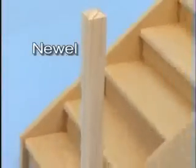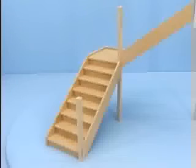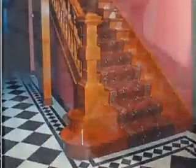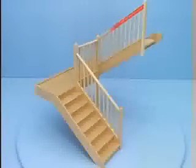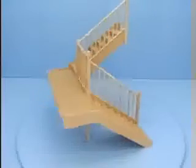The post at each end of a flight is called a newel. Newels are used to support a handrail and string and can be extended to carry the weight of a stair to the lower floor. They can be quite ornate and are often used as an architectural feature. A handrail is fixed parallel to and above the string. It acts as a guardrail and gives assistance to those using the stairs.